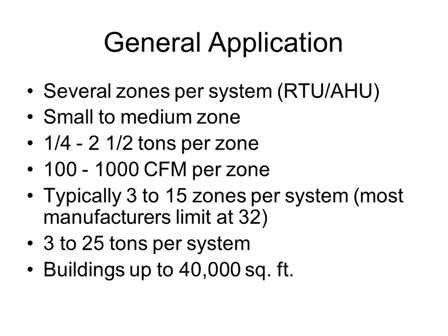I like to say don't go above 20. Usually above 20 tons, you have a cooling all the time load, and you can switch to VAV. You have some sort of internal zone that requires cooling all the time. So, and then another one, buildings up to 40,000 square feet, just a general guideline.